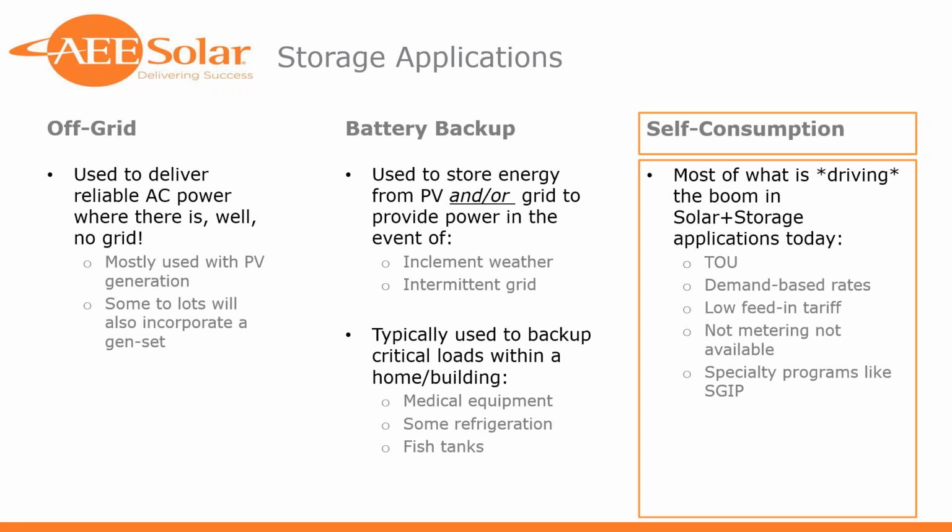Demand-based rates. We see this a lot in commercial, although we're starting to see it in utilities like Salt River Project, where you've got an energy component on your bill. You've used X kilowatt hours in these tiers, therefore your energy portion is this. You're also now starting to see demand-based rates where, given the automated meter infrastructure they've got, they know in a 15-minute period your peak kW that you're pulling off of the distribution system, and they're assessing you a fee based on that. So the name of the game here is putting some of those loads behind storage and making sure that they're not driving up your peak kW number.